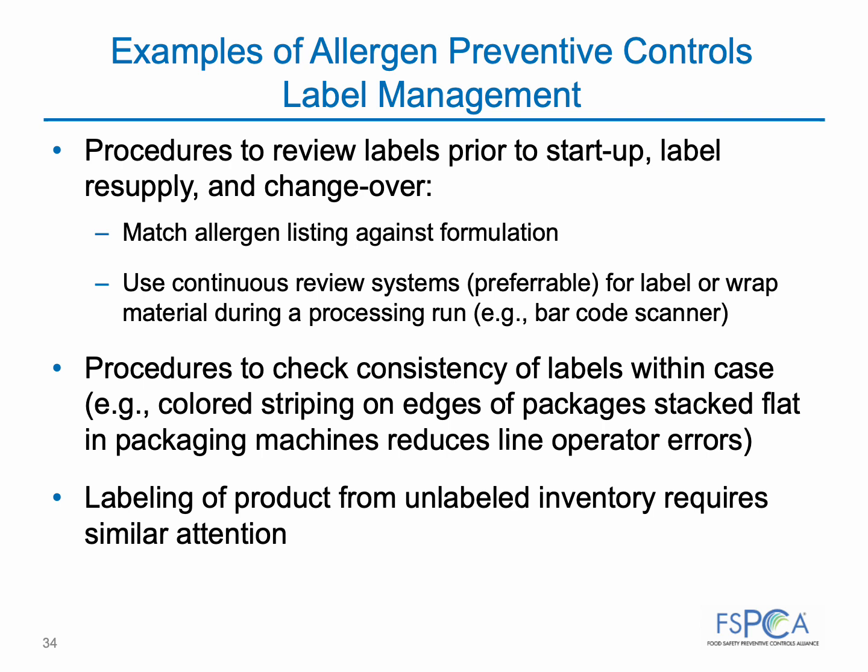Keeping accurate inventory records of labels and packaging can help identify issues. If the numbers do not match, it is likely the wrong label was used on a packaging run. Stage packaging so that only those needed for current product are in the packaging area.